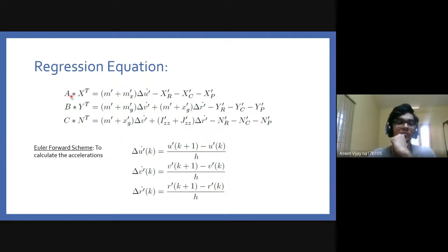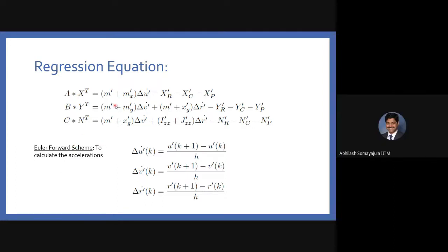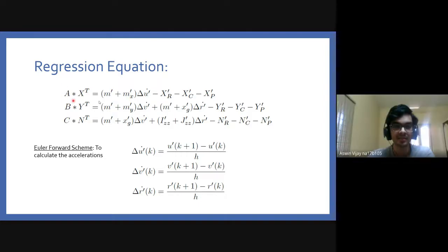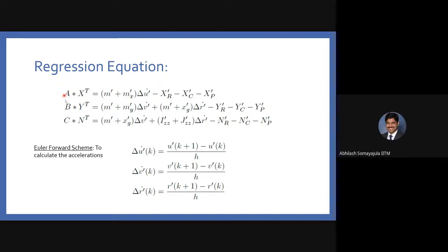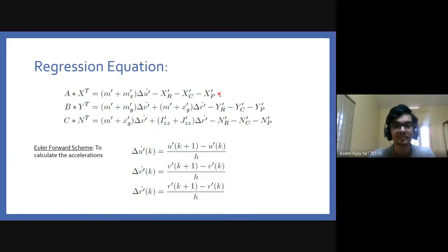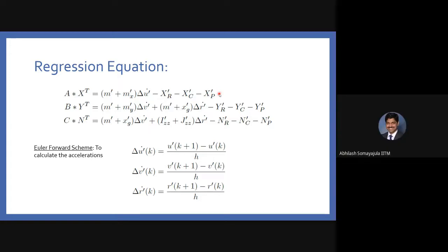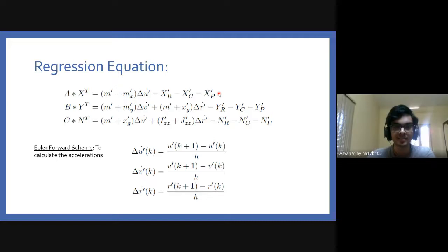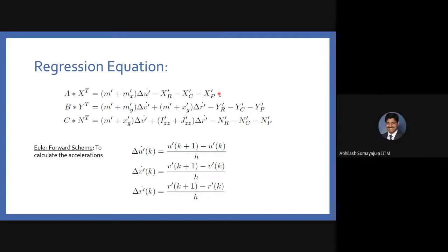Yeah, but it wouldn't work if your later readings are constant. In that case, it just becomes zero, right? And you're not doing anything helpful. For example, let's say I'm looking at a turning circle maneuver. That is what is happening. R will be zero. If you take a consecutive difference of R after it has reached steady state, it will be zeros, right? Yes. So it will actually not make an impact in getting R any better.